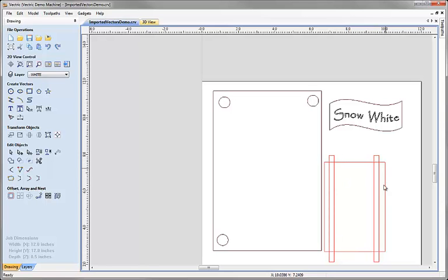But in this case I've deliberately contrived it so that we fail to find these because they weren't continuous in the file definition, and so we've imported these line segments. So that's another common problem: what you've got here is 4 open vectors and not 1 closed vector. If you get an error message when you try to machine something like this, which says that it's detected open vectors, this is the thing to look out for.